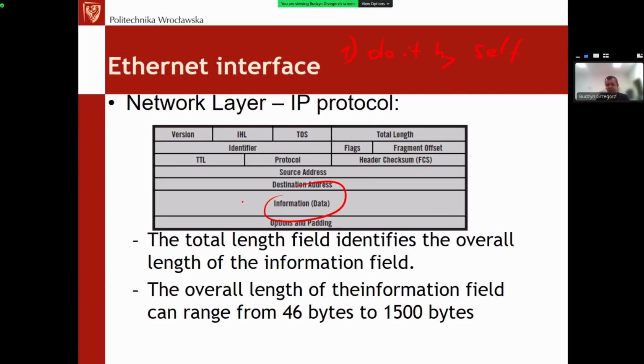You can imagine how much work it is. So solution number two is to take something more or less ready. Solution 2A is to use a kind of lightweight IP. There is such a TCP/IP stack, which has limited capabilities, which you can implement. We don't have time to get into this field, but it's there. It's included even in STM32 CubeMX.